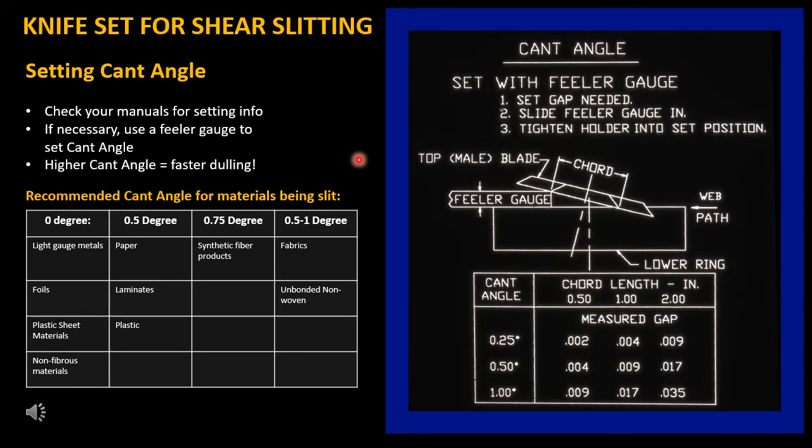We have listed some common cant angle and dimensional information for you to test top knife holder setups with. Who knows? Even if your holder has a preset built into it for cant angle, something may have moved. It's always good to double check. Cant angle or toe in is always a good place to start when you are trying to troubleshoot while your blades are dulling quickly and you're not getting the run life you anticipate.